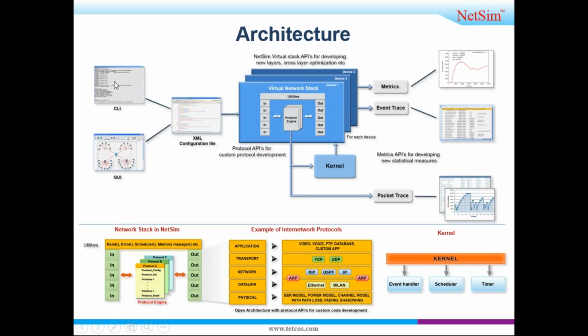So here you can see in the screenshot, it can be started through CLI and GUI, and when the network is designed using GUI, it will create an XML configuration file, which is further simulated through virtual network stack. And after the simulation, metrics will be generated. Then some traces like event trace and packet trace.